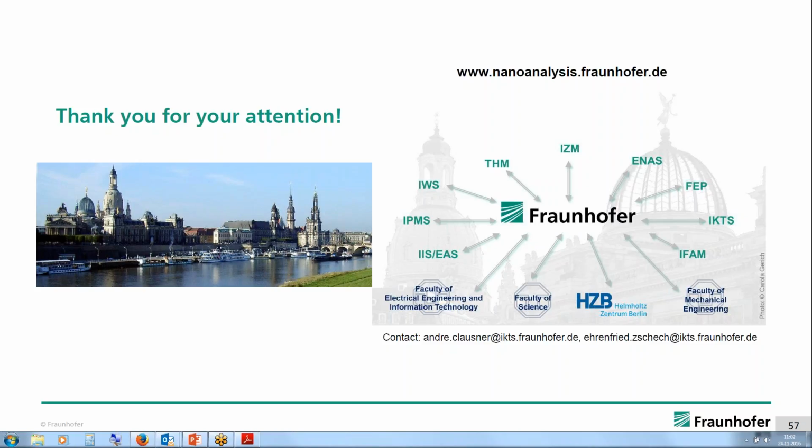Okay, now there's one question about the in situ SEM analysis, the drawbacks and advantages. Advantages, of course, you see what happens. You see if other cracks are forming, you see if there is plasticity, you see if there's pile up. Because in ex situ nano-indentation, you always have to assume that everything went well and everything is according to the theory you used. In situ, you see immediately what you're doing. This is the one positive thing.